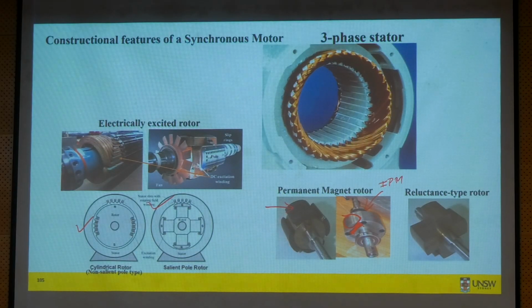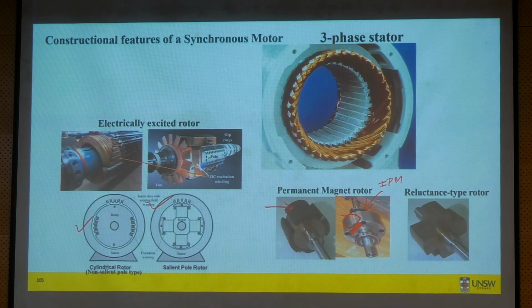In a conventional synchronous motor, salient pole machine, LD is bigger. Okay? In an IPM machine, it behaves like salient pole, but its LD is smaller. And why smaller? We can understand from this flux path. Okay?